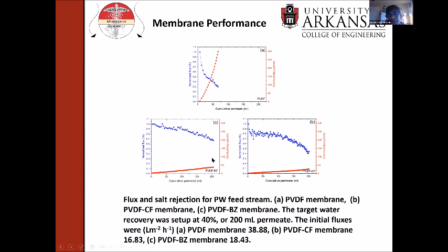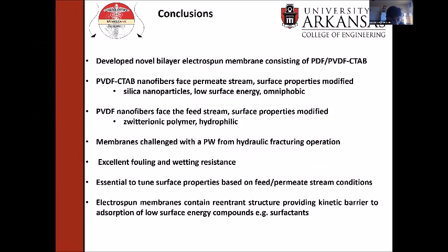I would also say that one of the things we learn is that we need to regenerate the membrane at some point, and regeneration typically is flushing with DI water. And if the membrane fails and you get water passing through, regeneration becomes very difficult. So you have to regenerate before you get breakthrough of water in the membrane. So I think I'm almost out of time.